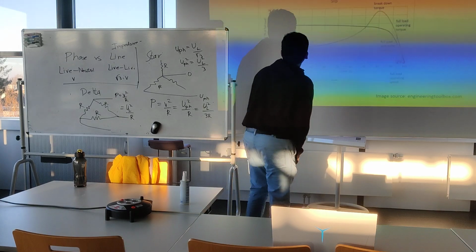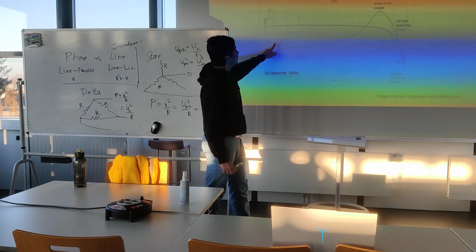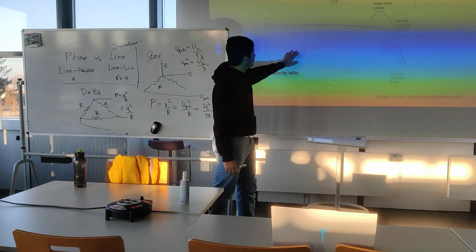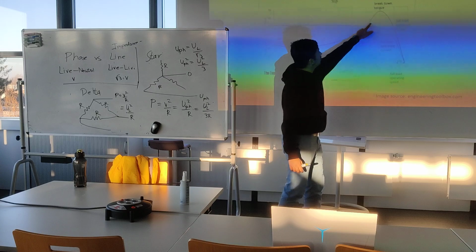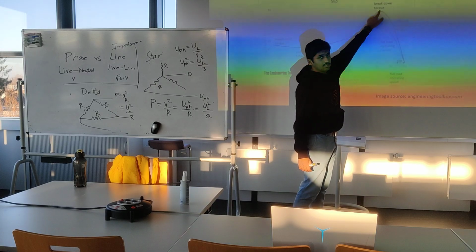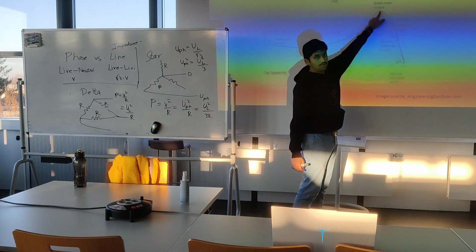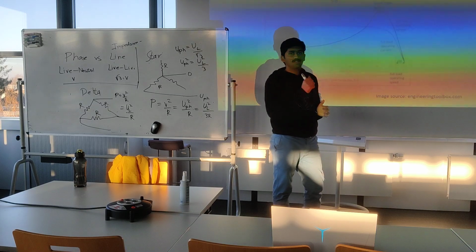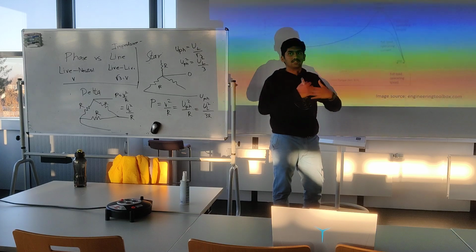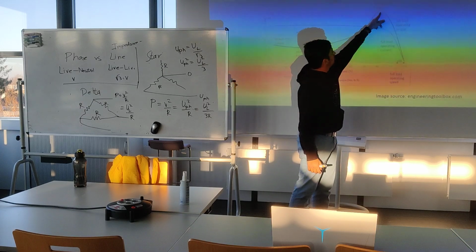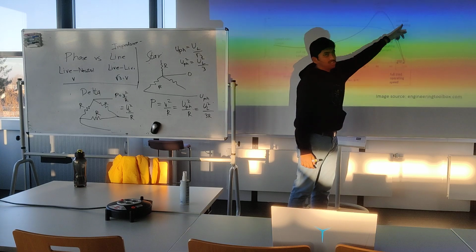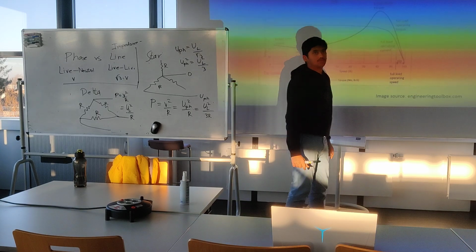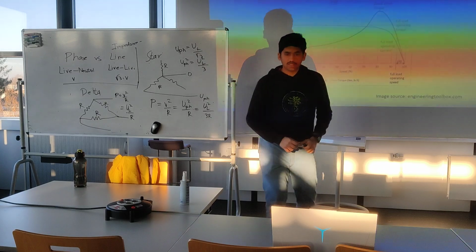So then the torque versus RPM graph. Here it's considered as locked rotor because it's at 0 RPM. And then we have the starting torque. This is the maximum torque you can do. It's called breakdown torque. If you try to put any more torque load, it will just stop. It won't rotate further, and then it will just make heat. But the nominal operating point, called full load, is here, and the slip is somewhat small. Slip is a new thing that's being introduced here.